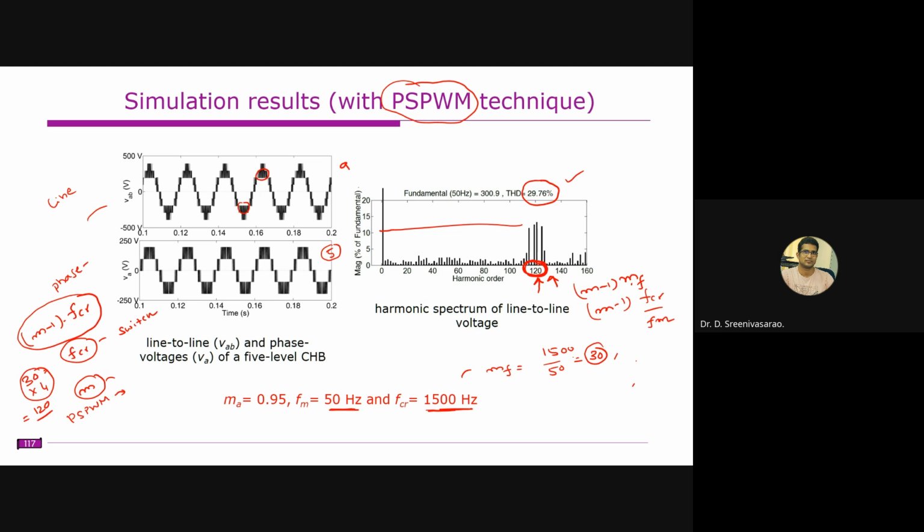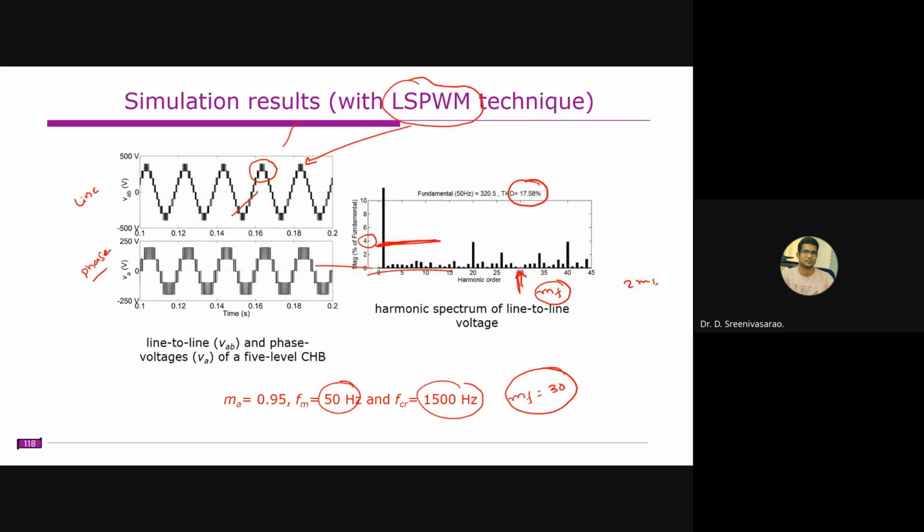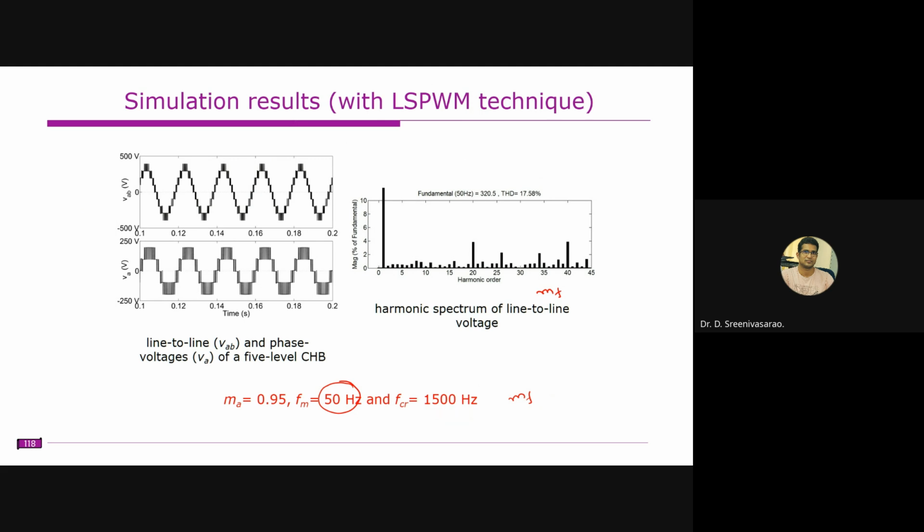All right, so the meaning is that this level shift PWM technique gives the best harmonic performance. In fact, for any PWM technique, this is a benchmark. No one will get performance better than this. This is the best THD that one can obtain with any method. That's why, when people invent a new PWM method, they normally compare it with the level shift PWM technique itself.